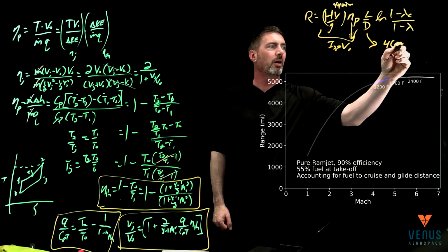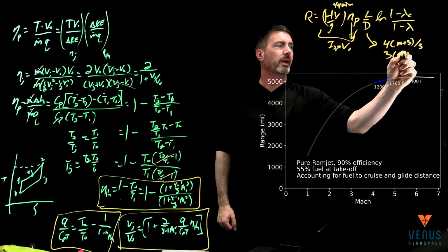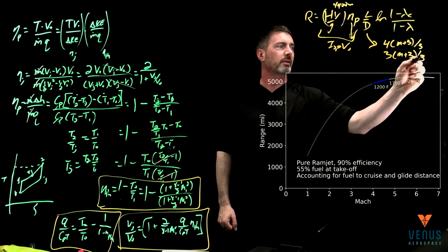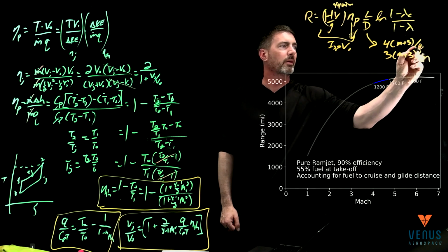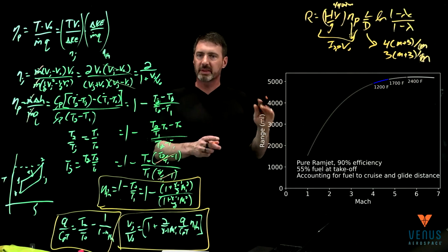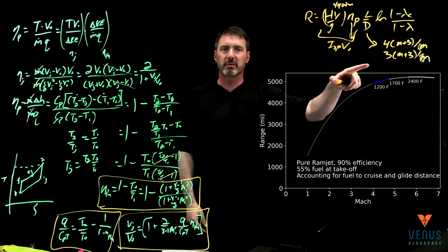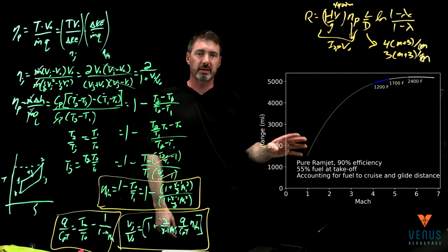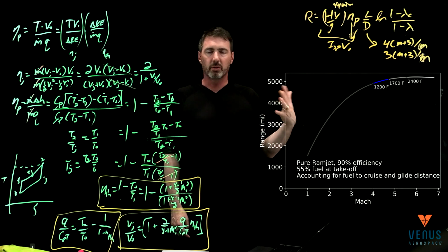It's somewhere between Mach, these are usually what is shown when you're doing L over Ds. That's kind of the, over Mach. Those are kind of some acceptable ways of estimating L over D. So I'm choosing the conservative one when I'm plotting this to get that range. And I'm using kerosene, jet fuel.